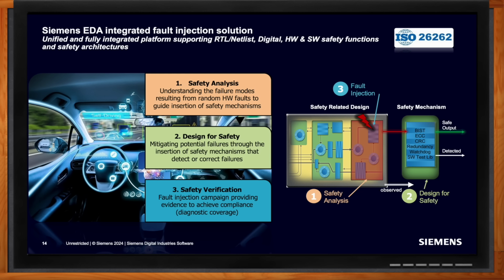It's using standard fault optimization techniques like cone of influence, both forward and reverse, things like shallow fault collapsing and equivalence, and things like statistical random sampling. The idea is to generate the smallest but most highly optimized fault list to meet your ASIL B, C, D needs, depending on the project.